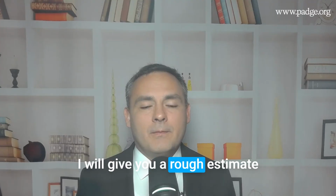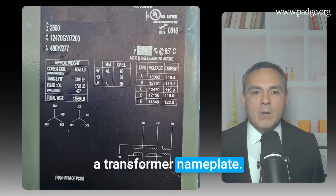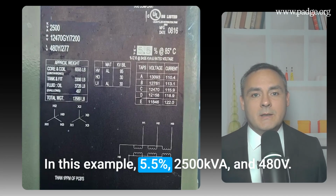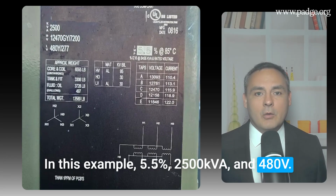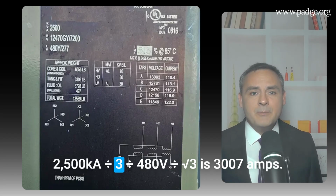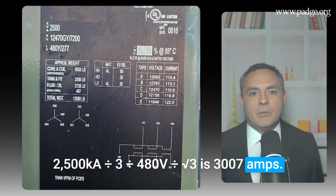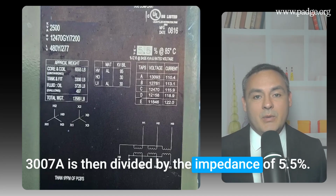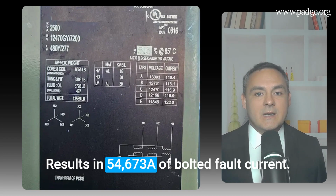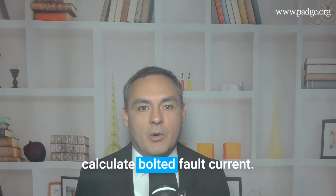I will give you a rough estimate that gets you close by looking at a transformer nameplate. Look for the impedance, kVA, and voltage. In this example, 5.5%, 2500 kVA, and 480 volts. 2500 kVA divided by 3, divided by 480, divided by the square root of 3 is 3007 amps. 3007 amps is then divided by the impedance of 5.5%, which results in 54,673 amps of bolted fault current. That is a crude way to calculate bolted fault current.